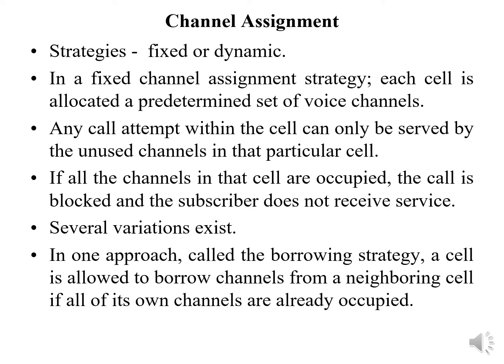Next, we can see the channel assignment. The strategies are classified into fixed or dynamic. In a fixed channel assignment strategy, every cell is allocated a predetermined set of channels. Any call attempt within the cell can only be served by the unused channels in that cell. If all the channels in that cell are occupied, the call is blocked and the subscriber does not receive any service. Several variations of the scheme exist. In one approach, called the borrowing strategy, a cell is allowed to borrow channels from a neighboring cell if all of its channels are already occupied.